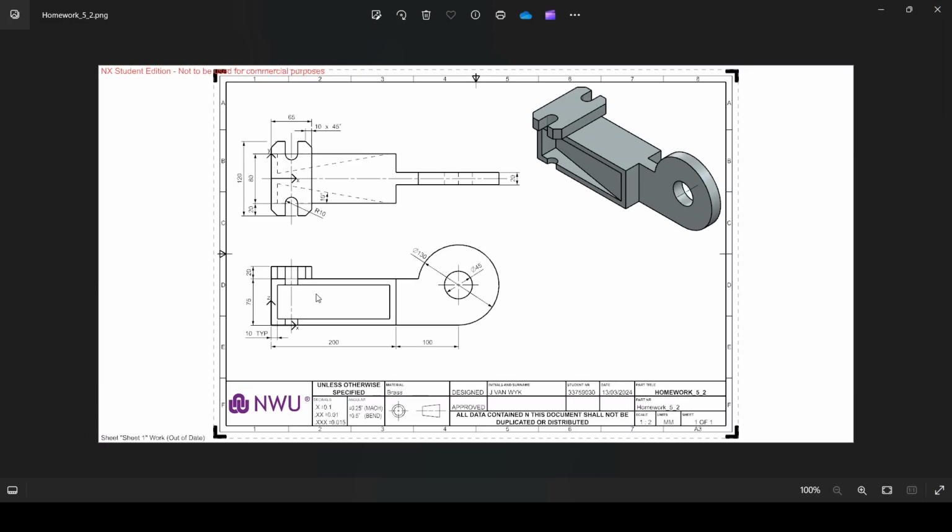It's important your origin is correct. Some of you are still not putting the origin in the correct position. Here you can see it should be at the front of the part in the middle, so the part should be symmetric around that. Yeah, that's important because when we're marking, the values that you add are dependent on this origin.